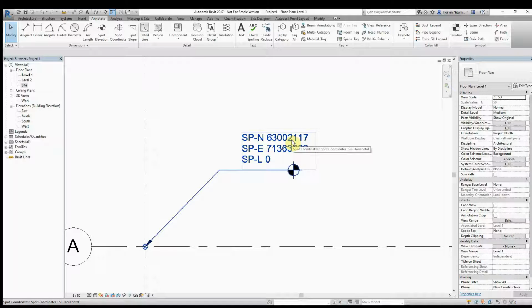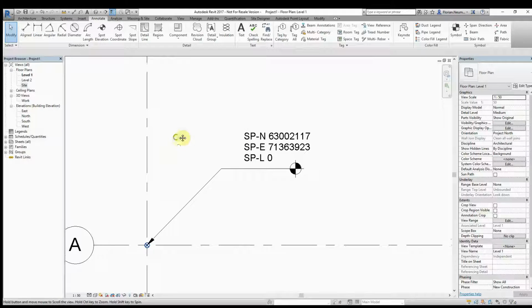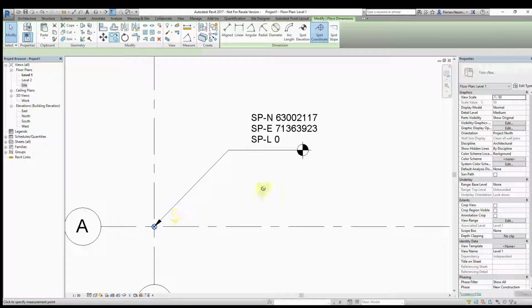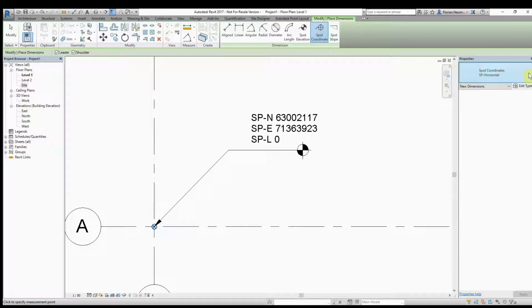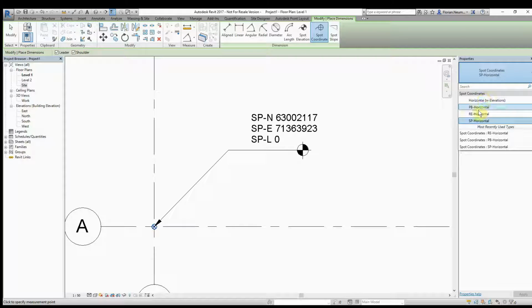And please notice that we actually brought this in even 63 something kilometers away from the survey point without any issues. Why? Because there was no geometry on my origin in my DWG file. That's why we had no issues. So hence we see we can bring this in without any problems. Okay, good. Let's quickly find out where the survey point actually is. Maybe we just want to get a little bit more project base point quickly on here as well.